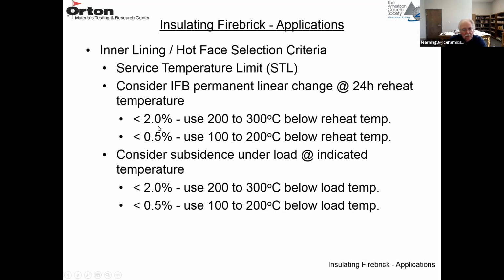If the reheat change is less than 2%, you can use the material at 200 to 300 degrees C below the reheat temperature. If it's less than 0.5%, you can use it 100 to 200 degrees below the reheat temperature. Those limits give you the use temperature where no more shrinkage should take place.